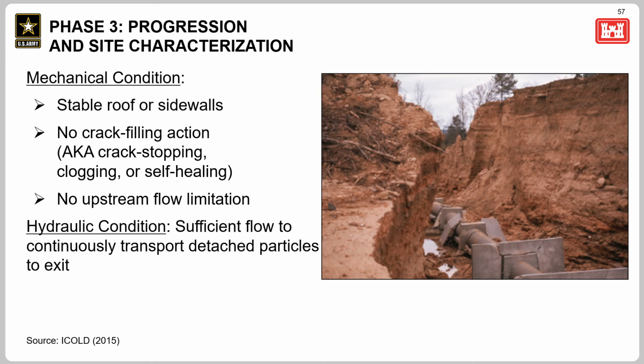Is there an upstream zone that supplies particles or a downstream zone that traps the eroded particles? So is there some kind of filter action or clogging action that might go on? And then is there an upstream hydraulic cutoff, that is, a zone of finer grained granular material, or a concrete face slab, or a core wall, or a cutoff wall that helps restrict the hydraulic conditions?